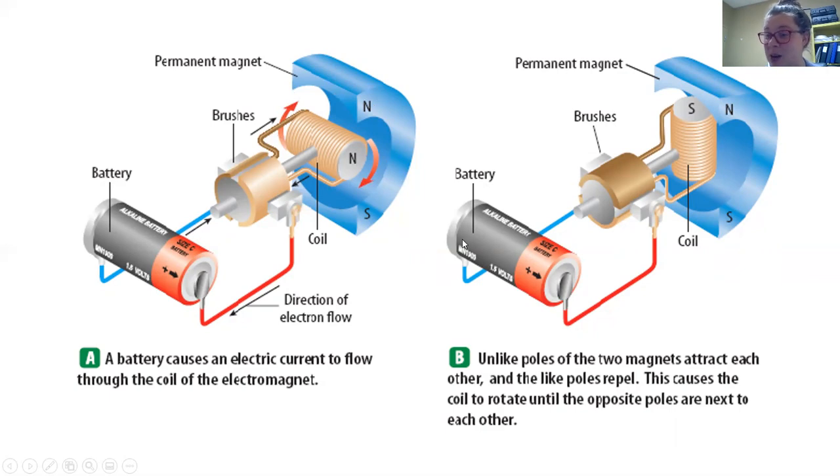But yeah, if we had a magnet, we could easily create a little motor. And I've done this sometimes just using a simple coil of wire and a battery and a magnet on a table. You can actually get rotation to occur just by doing something like this. To simulate brushes, you leave insulator on half of your wire that makes your coil, and it's actually a cool little experiment. If you want instructions to give it a shot, I can send you instructions for that.